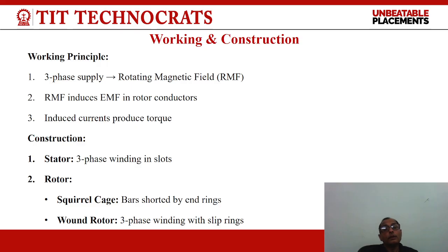Now if we talk of the working principle of a three-phase induction motor, we have a stator and a rotor. The stator is fed through a three-phase AC supply. As a result, it produces a rotating magnetic field around the rotor. This synchronously rotating magnetic field cuts the rotor conductor. As a result, an EMF is induced in the rotor conductor as they form a closed circuit. This causes a current to flow in the rotor conductor, which again produces a rotor magnetic field.